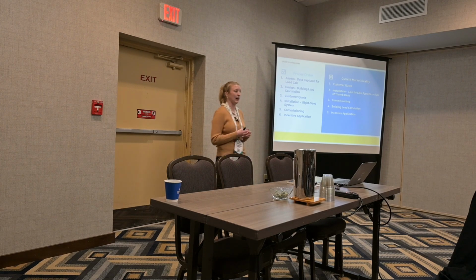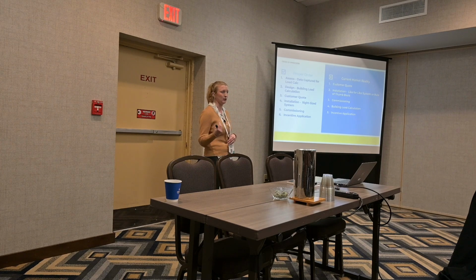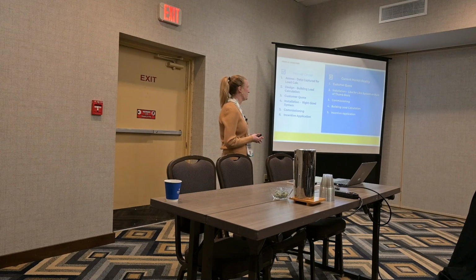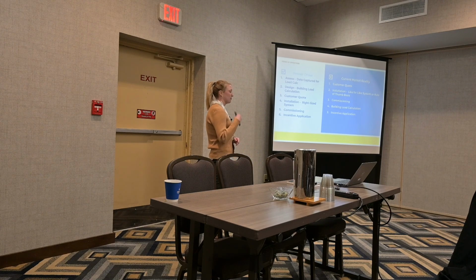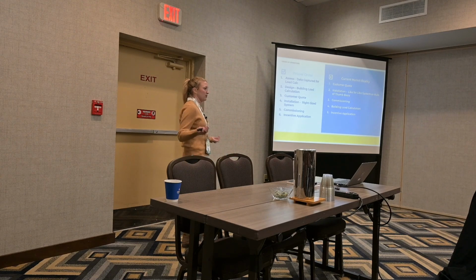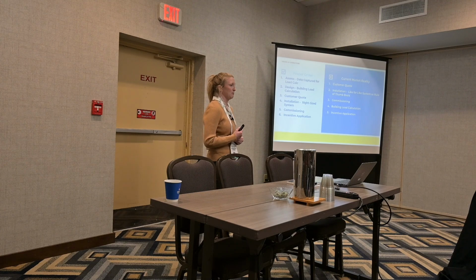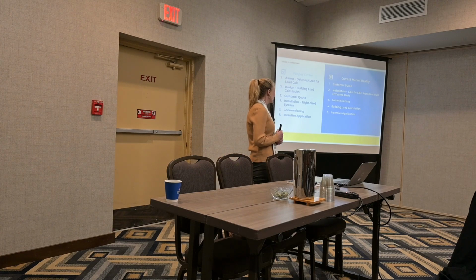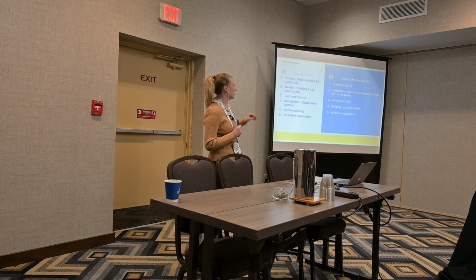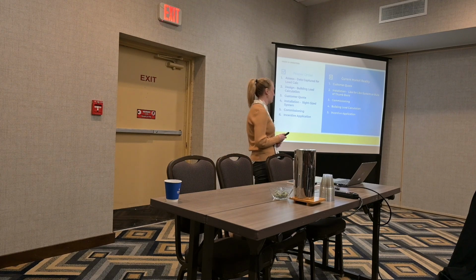As the quality control service providers for the New York State Clean Heat Program, we've seen that some contractors out there are actually performing the load calc later on in the process, just before the incentive application. They were originally just installing a like-for-like system based on what the original equipment was sized to, or using a rule of thumb, which is going to lead to an oversized piece of equipment, uncomfortable conditions, and poor public perception of heat pump technology. So you want to make sure you're conducting the load calculation at the beginning of the process.